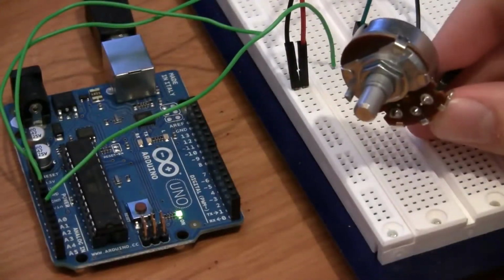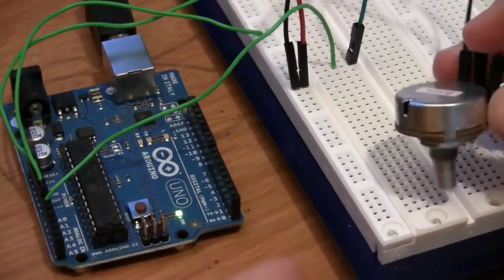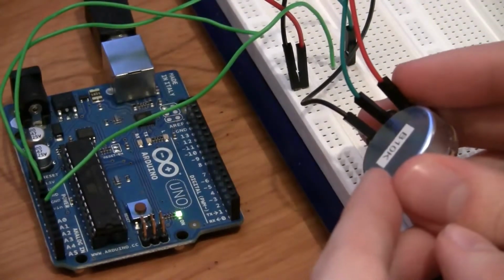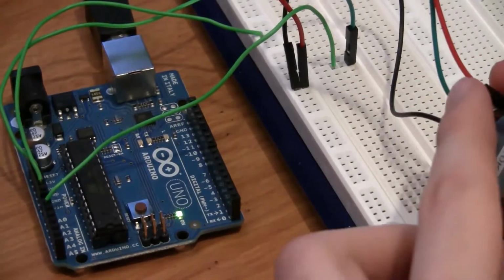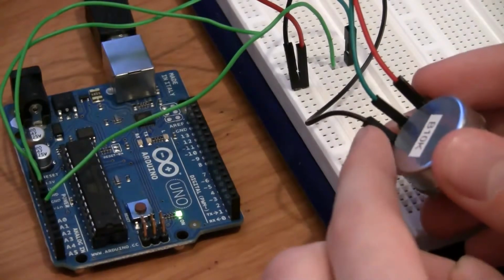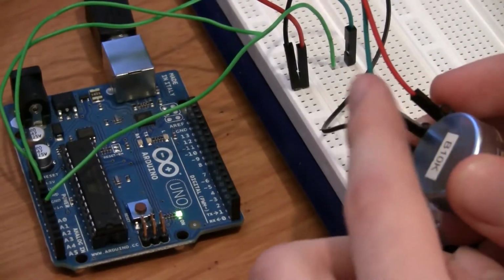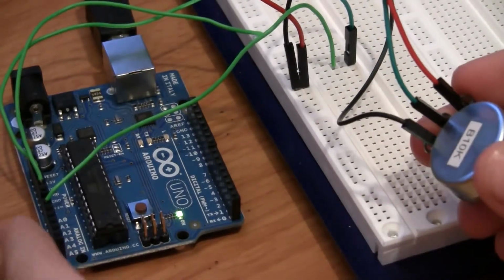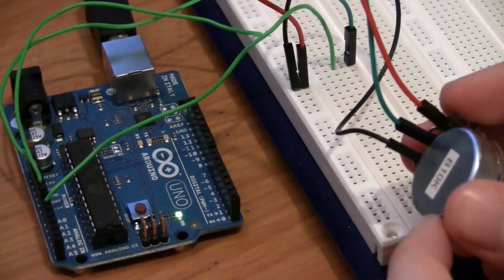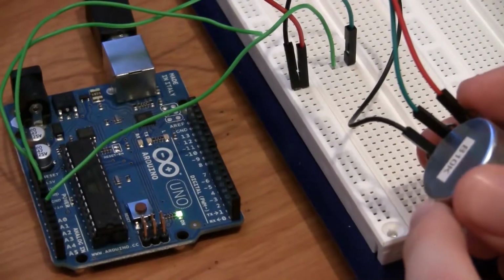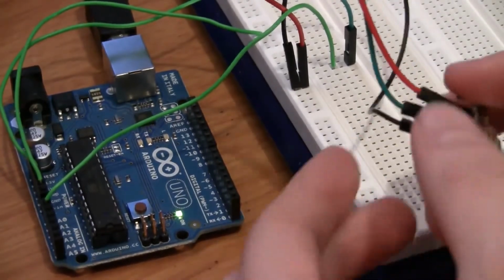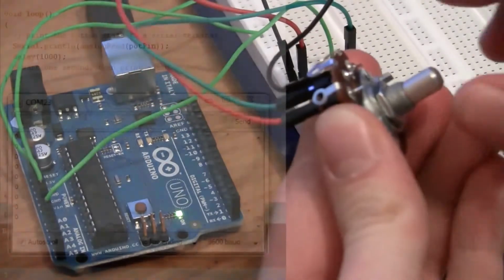Here I have a simple potentiometer, usually abbreviated to a pot, and I have it hooked up to one of the analog input pins on the Arduino. We'll be talking a little bit more about analog input in some future episodes, but basically we have our red connector on the pot, which goes to our 5 volts, ground, which goes to ground as I showed in the diagram, and then the middle one is the one going to the analog input pin on the Arduino, which is analog input 0. The Arduino has 6 analog inputs, each of which can read values from 0 to 1023 depending on the voltage from 0 to 5 that you give them. And you can change the voltage reference too, but we'll talk about that a little bit later. So, let's see what happens when I turn our potentiometer.